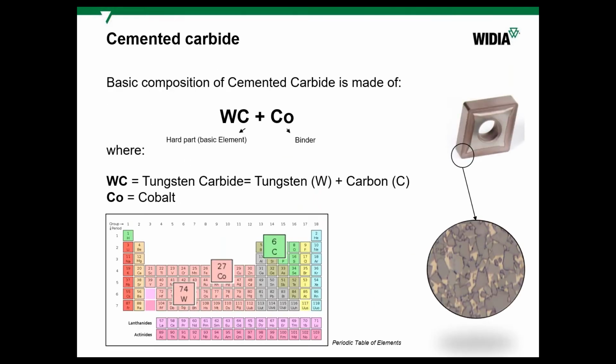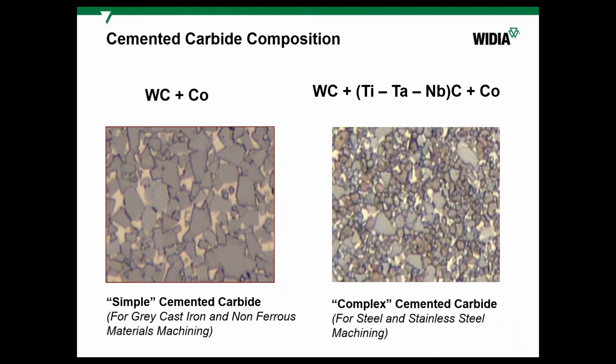Also, why it's called cemented. Basically, it's hard particles cemented or stuck together by cobalt. So there can be different substrates, one carbide or double or triple carbides. Additional carbides were added in the 30s of the previous century to WIDIA grades, and after that to other grades of other companies. And the purpose of them is to achieve better